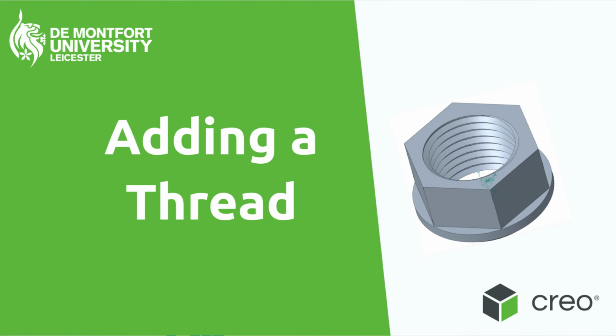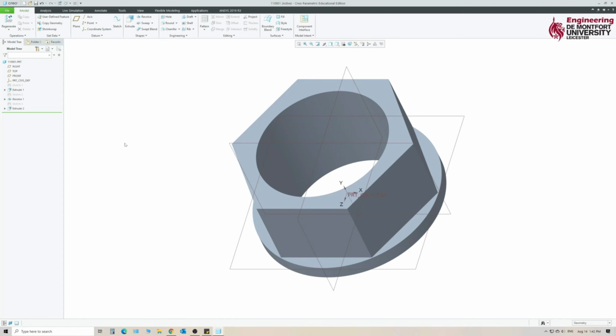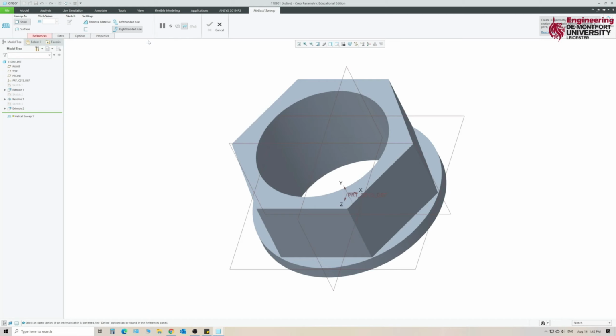In this video, we're going to be having a look at how we can use the helical sweep tool to add material, so we can add a thread. So in order to start the sweep, we just go to sweep, helical sweep. Again, you'll notice that the reference tab needs some information. So first of all, we're going to add the sweep profile. So we're going to define this.